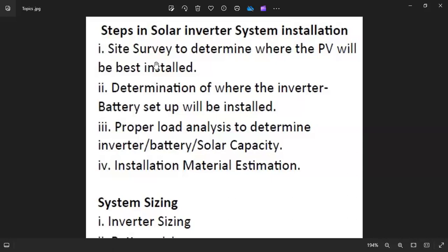So now imagine it is installed in a confined space, and you have an issue with overcharging. You know what will happen? A lot of dangerous gases would be emitted in that confined space. So in a nutshell, it's not advisable to install these two batteries in a confined space, you understand, because they need ventilation.